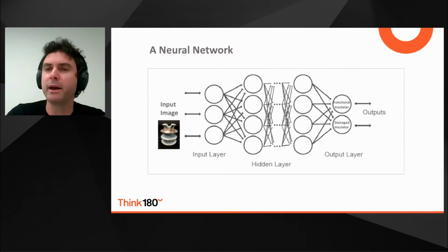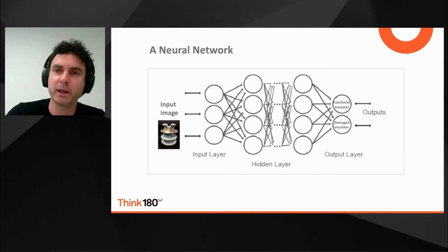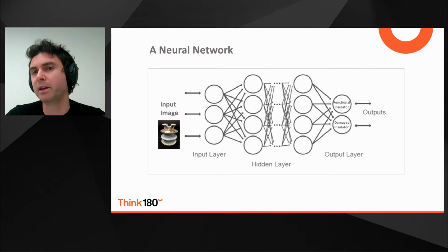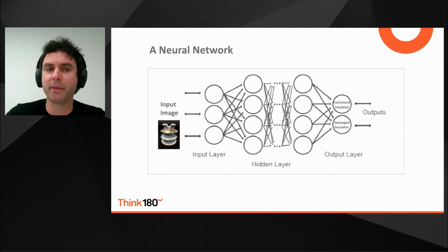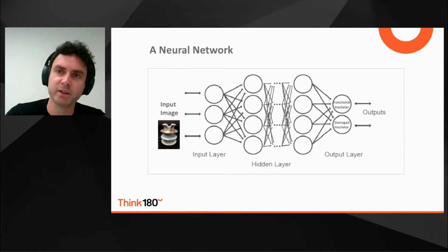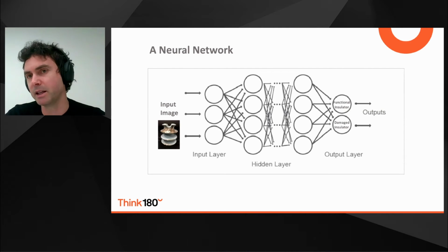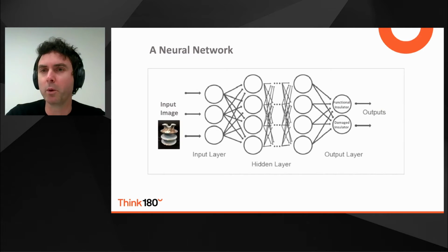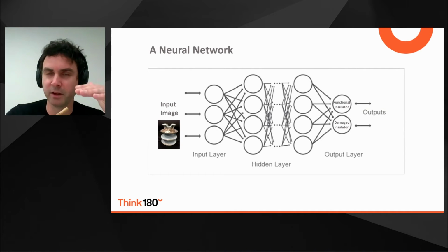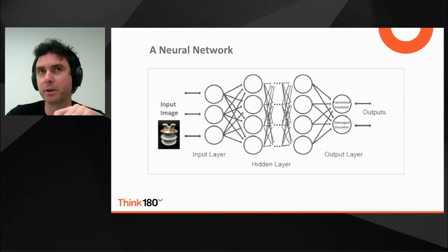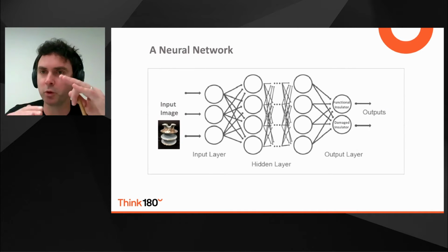It can learn by showing it data and then feeding back what it knows about that data. So we show it a damaged insulator, tell it it's seeing a damaged insulator, and then the neural network can learn, as it's called. And what's happening inside there is all the ties between each neuron, the weights, are being adjusted using a very complicated mathematical algorithm, backpropagation, to adjust all the weights in the model.